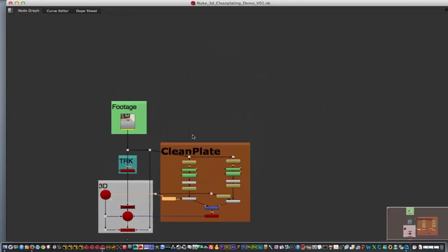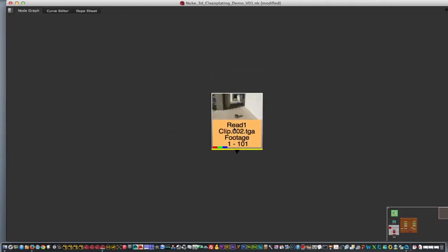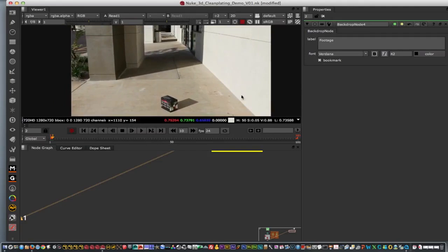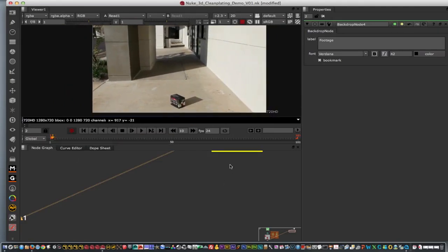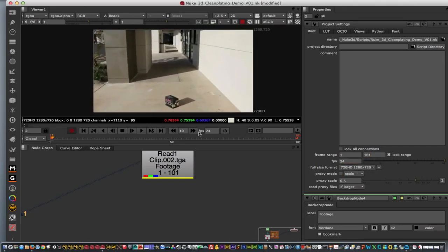So let's go ahead and start. I'm going to duplicate this footage, and this footage is in your assets folder. You're going to have two clips, so make sure that you drag one of those, the one you're going to be using. The next thing we have to do is set our project. In this case, our footage goes from 1 to 101. So let's hit S to set our project to 1 to 101, 24 frames a second, and 1280 by 720 for the scale.